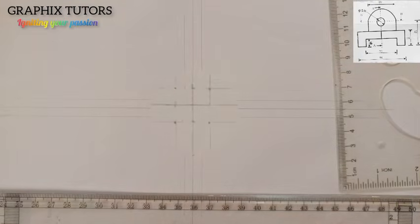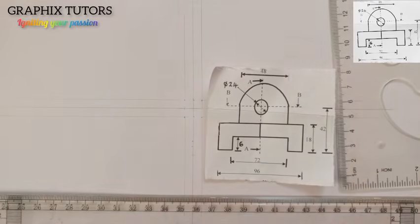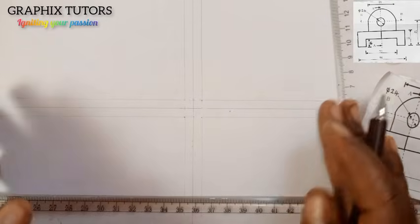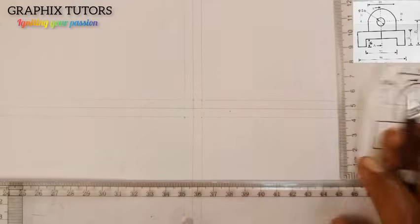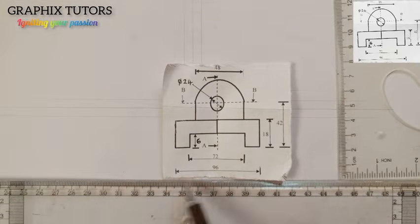So I'll start taking this drawing, start measuring. Now this is the front elevation of this drawing. If I draw it above the x-axis, it means it's in first angle projection, right? So I can choose any of these quadrants here. I'll choose here and I'll start measuring. If you look at this carefully, the entire length is 96.